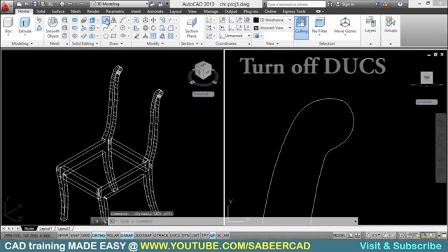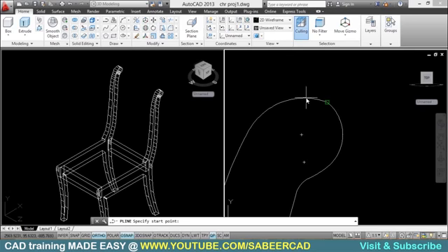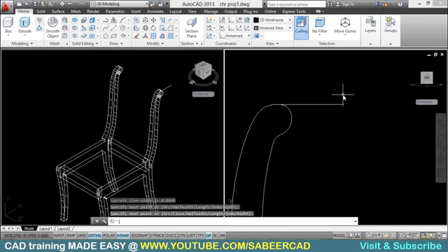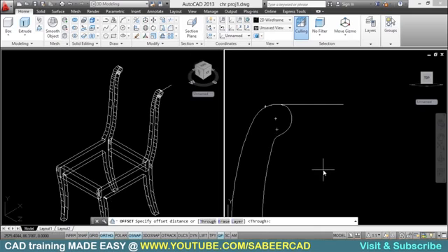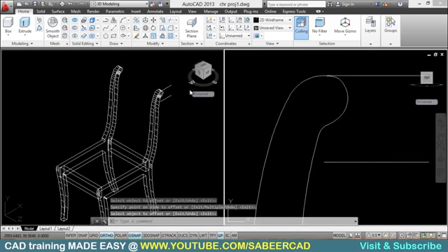I'll go to the polyline command and start my polyline somewhere from this nearest point, and I should hold down the shift key and right button of the mouse simultaneously to get the O-snap menu. And I'll select the nearest option from here and draw a line with arbitrary length. Now I'll give the offset command with an offset distance of 8 cm, select the object to offset and the side to offset. Okay. Now let's create the polyline.